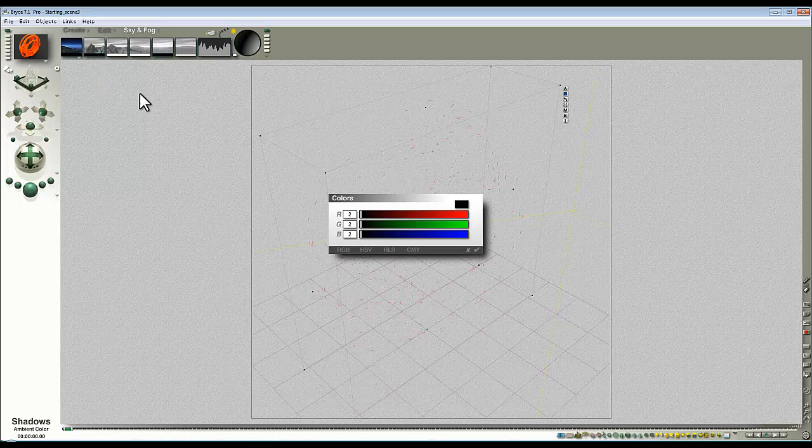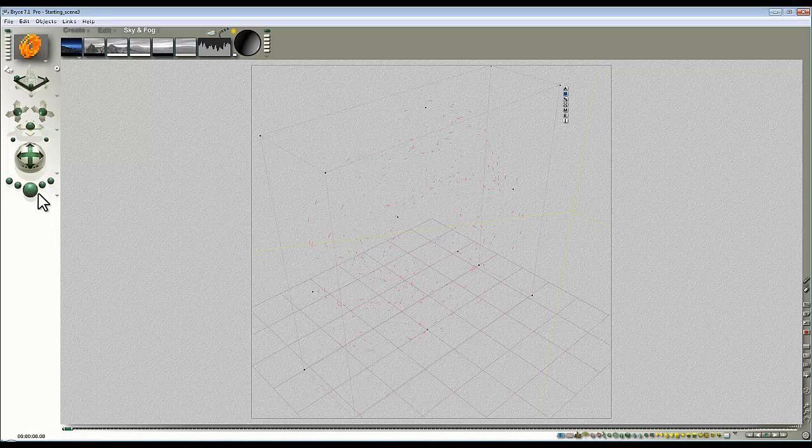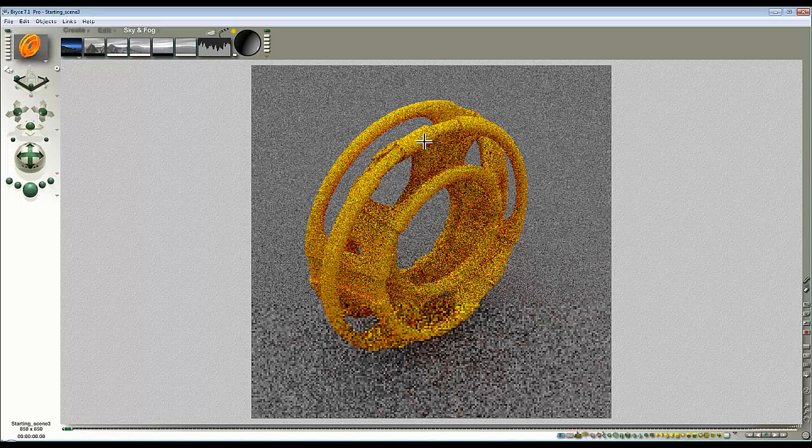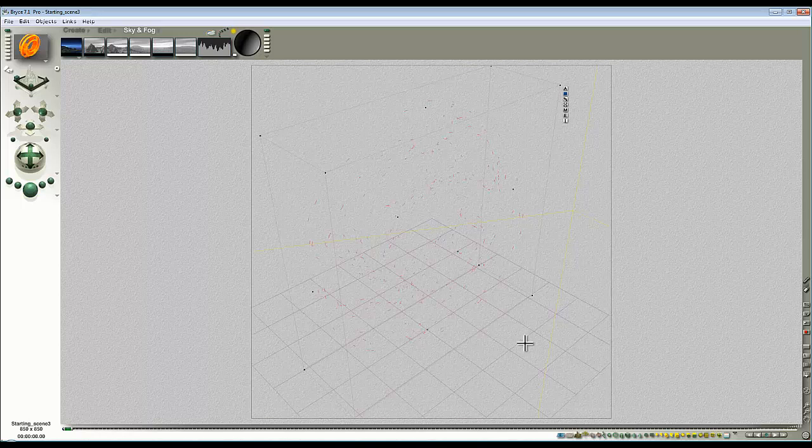So if I give that a little bit more light, so I'll take that effect up to say 4, and I already know that I can to some extent increase the contrast in this by providing something to take light out, which is why I set the ground quite dark. And I'm going to bring the reflection back in because I think it might be nice to introduce, in fact I'll take the diffusion right out so it's just a black surface, and then if you use metallicity it'll make it darker towards the camera.